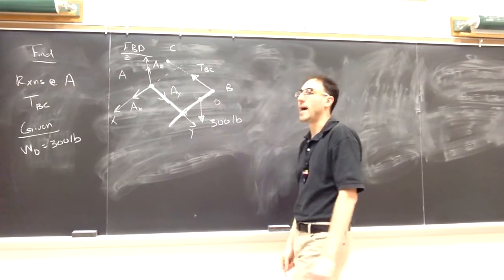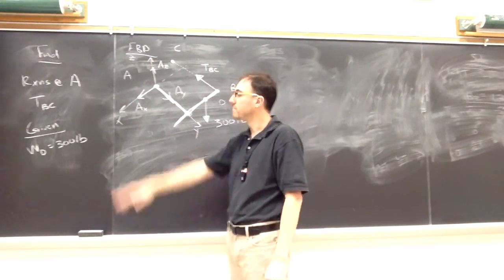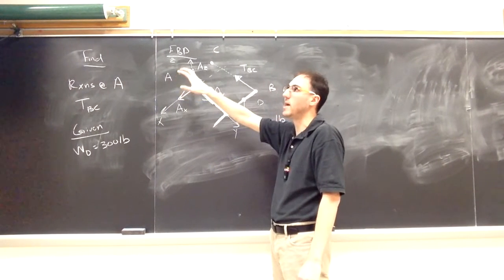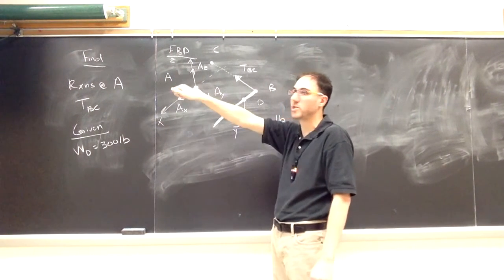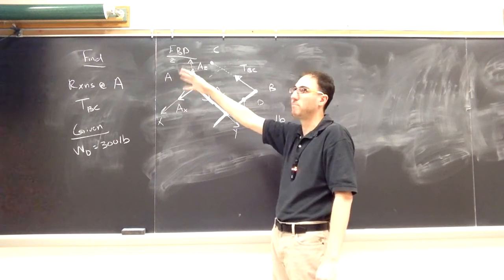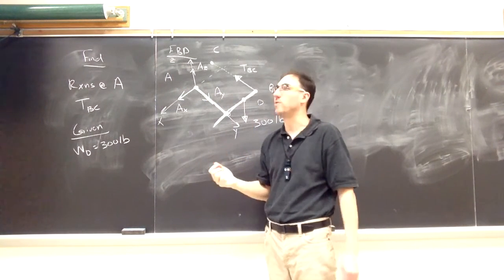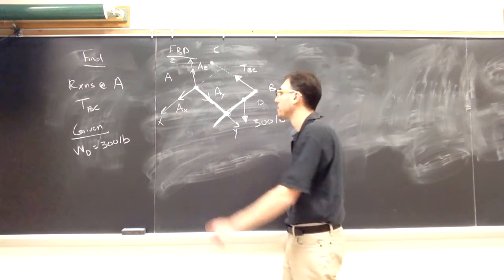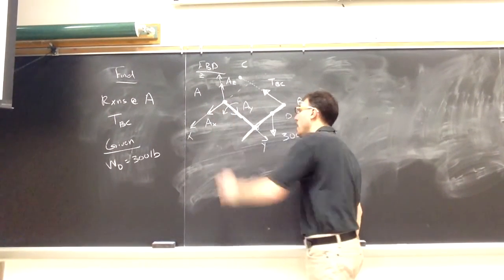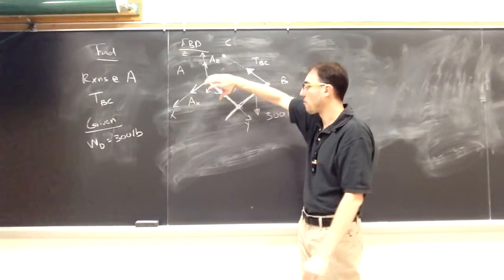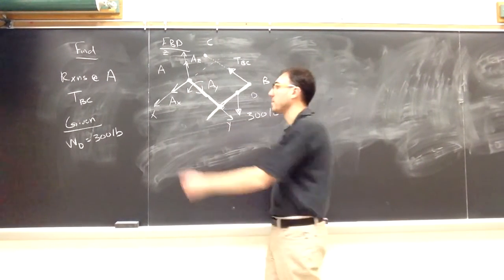Can't rotate around the y-axis. Right? It can't because of the pin. If we tried to twist it around y, it would bash into the bracket there. We cannot rotate around y, so there is a couple. I can draw that. I'm going to assume in the positive, around the positive y-axis, and I'm going to call that My.